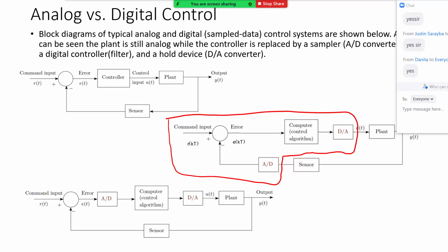And again, if you remember from when you design a digital filter, if you designed a low-pass filter for a signal that is sampled at 1 kilohertz, if you go apply this low-pass filter to a signal that is sampled at 2 kilohertz, then the whole filter behavior is going to be totally different. The cutoff frequency, all of these things are going to move according to the sampling time that you're using. Again, we're going to be discussing these and emphasizing it throughout the semester.